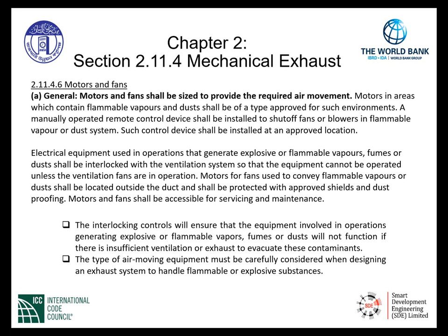Now, the very last item that we need to pay attention to as well is any motors or fans that are used to convey flammable vapors or dust, things of that nature, must be approved. And shields and dust proofing, the motors and fans also need to be accessible for servicing and maintenance.